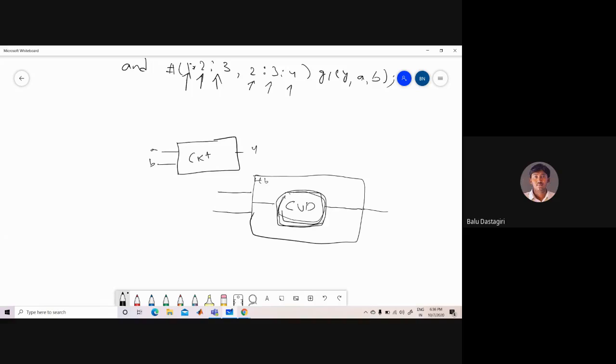So for example, first the module syntax of a test bench. Module name: this can be any module name, but it should be a proper identifier. Here there is nothing to give for the list of port names, so no need to give the list of port names. Next we have to specify the registers. I'm not exactly following the same syntax as in the textbook; I'm just telling you the easy method of how to write a test bench.